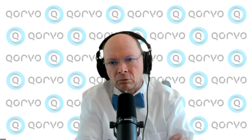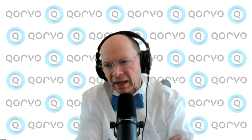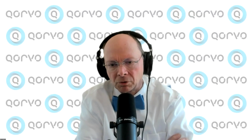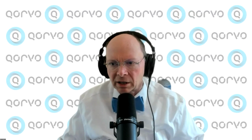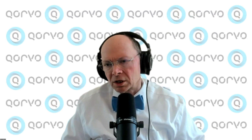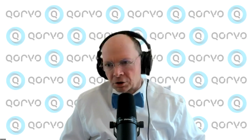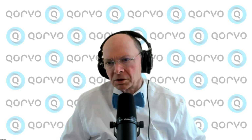Without characterizing the shot noise, it will dead reckon what the noise would be from first principles, that it can't be less than this. It will compute that, where most SPICE programs actually get that completely wrong, by orders of magnitude in the triode region. The noise of Berkeley SPICE doesn't handle the noise of a JFET in the triode region at all. It just ignores it, basically.